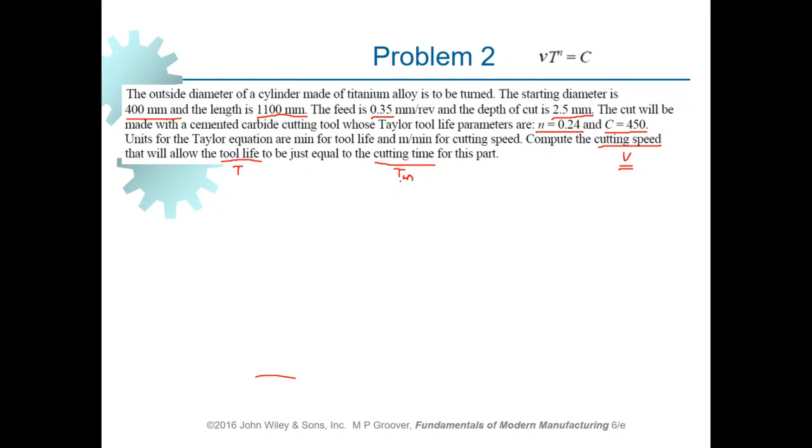Machining time equation, we had that before in previous lectures. We had equations making it possible for us to compute the machining time of cylindrical workpieces. And that is the one which I am taking from the previous lecture. This one is the equation for computing the machining time in straight turning operations. What do we have in this? Machining time TM. D is representing the diameter of the workpiece. L is its length. f is the feed, and V, of course, is the cutting speed.